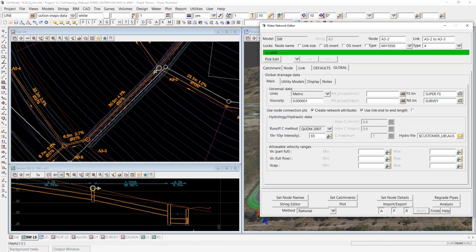And if I just hit the apply button there, you can see the gap in the arrows on the section view has just disappeared, and all of the numbers change slightly, including the grade. It has an effect on the pipe grade as well. And my perfect 0.5% grade is no longer 0.5% because my pipe lengths are now defined a little bit longer than they were. Nothing has actually changed physically, it's just the definition there.